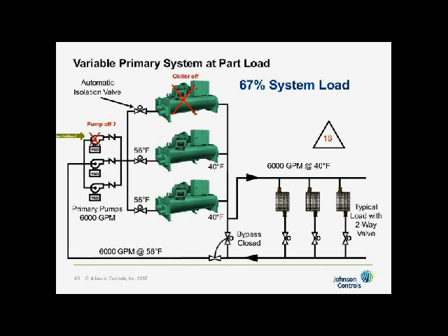Those are algorithms that something like a CPO would do. I've used the term CPO several times. That's chiller plant optimization for those who may not know, and that's what the third webinar will be all about. Anyway, I can choose here, but the point is that I can now turn this chiller off. So if I have 3 constant speed chillers that don't have CPO on all the auxiliaries and so on, now I don't have to run more chillers than I need. I can just overpump these 2 chillers when I have low delta T, which is now.